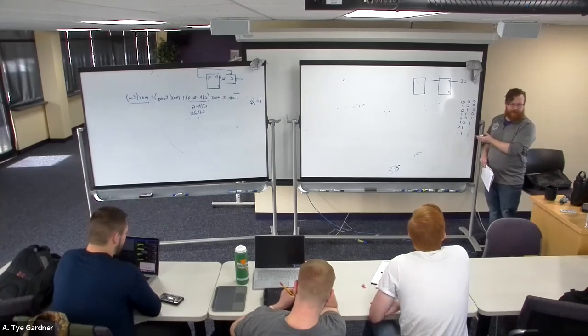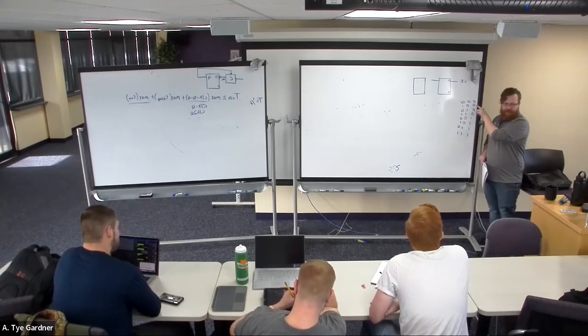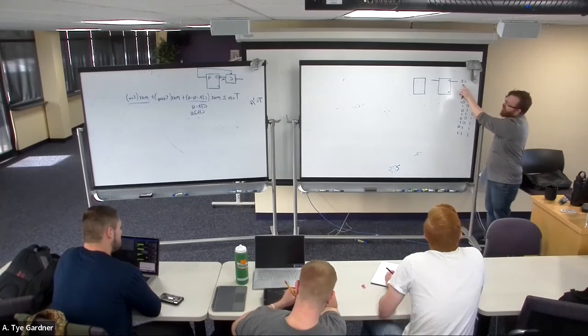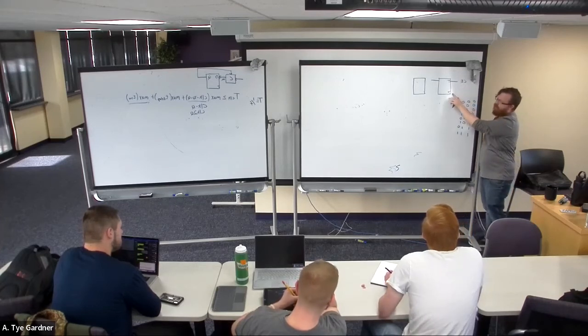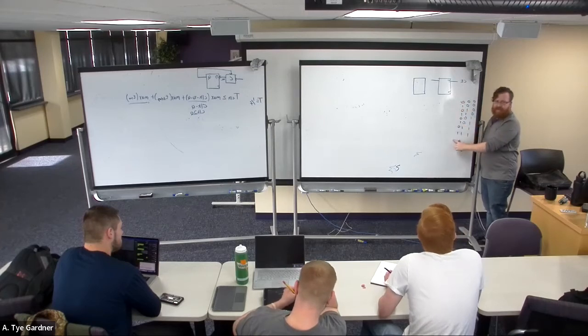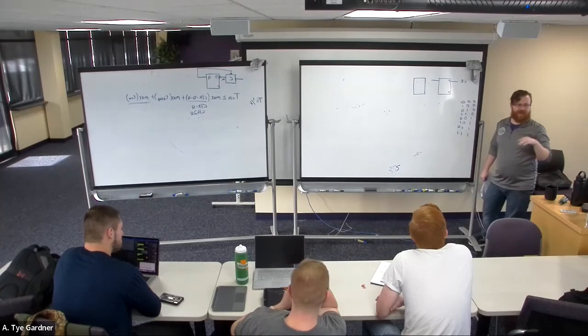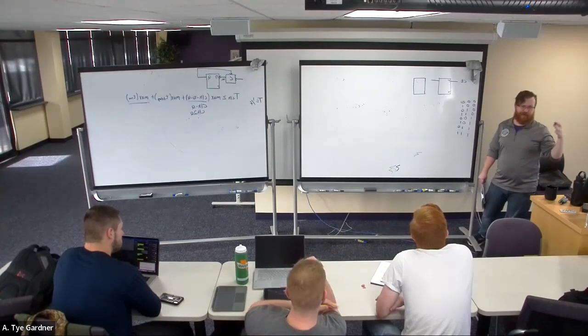Remember this pattern from our truth tables? Remember how we're counting? See this clock enable? If this clock enable is 1 and a rising edge happens, it does this. I've made the first column. I've made a 1-bit counter. Just 1 bit just goes 0, 1, 0, 1, 0, 1.